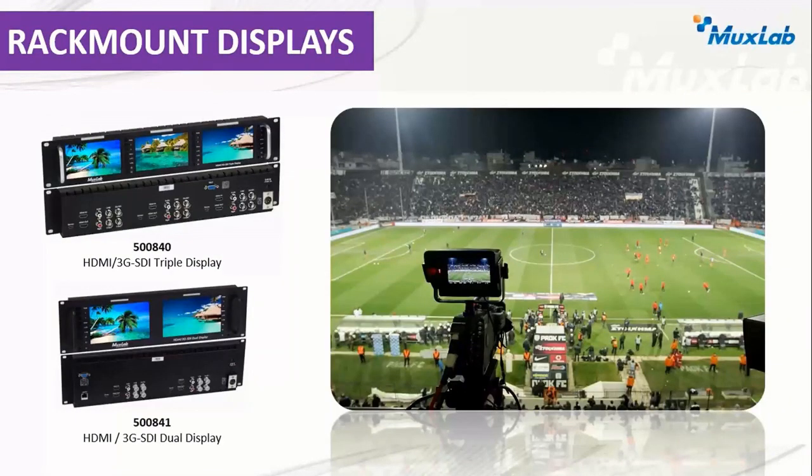And lastly, we've got some monitors that are rack mountable, a dual version and a triple version. These are used in wiring closets so that if you've got signals going out into a large facility and you can't look at the TV output and you want to get a glimpse of it in the wiring closet, these devices have a loop, an in and an out, and a loop out for both HDMI and SDI, 3G SDI. And so you can basically spy on and get a duplicate of what's being sent out into your infrastructure, just to make sure the signal is correct. Okay, it allows you to monitor those signals.